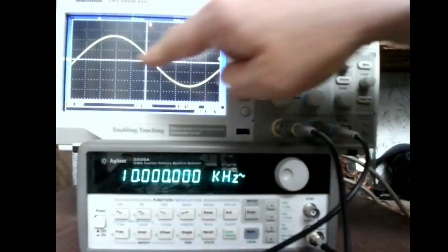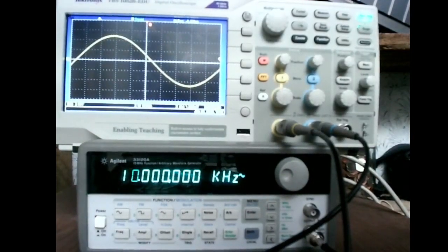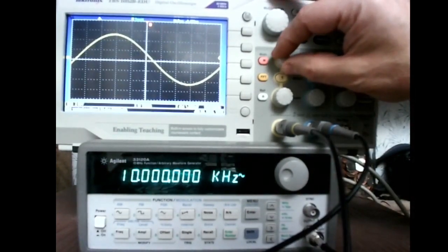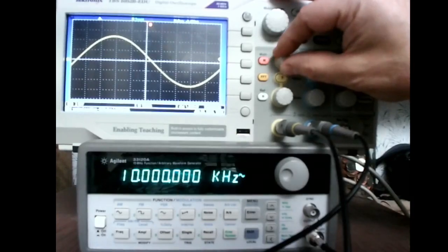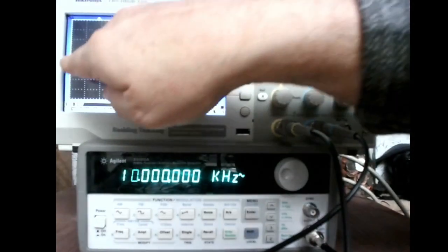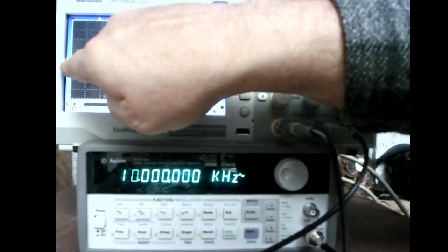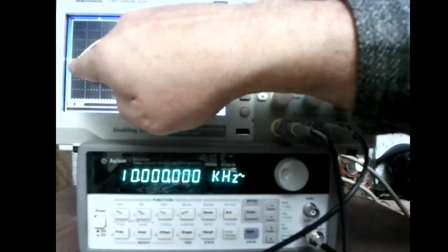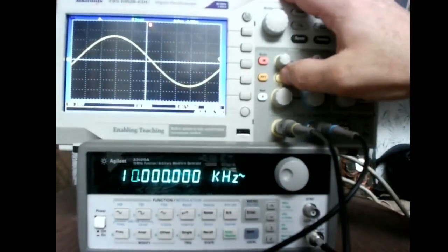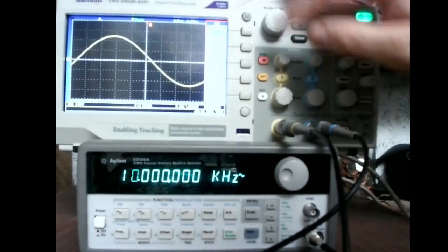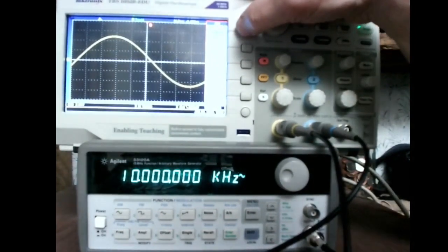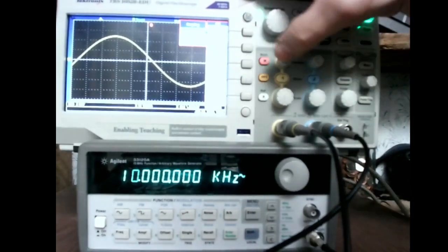All right. But as you can see here, now we're showing a sine wave, and the ground point of that sine wave is this little flag or this little marker over here. That shows you where ground is equal to 0. You can also view that by pressing this. You see it says DC coupling, so you can do what's either called DC coupling, ground, or AC coupling.